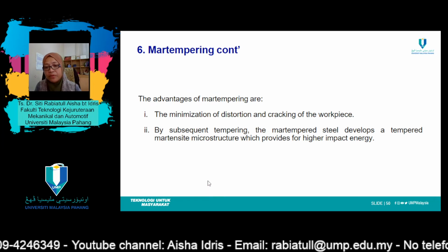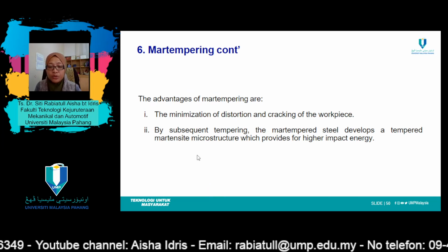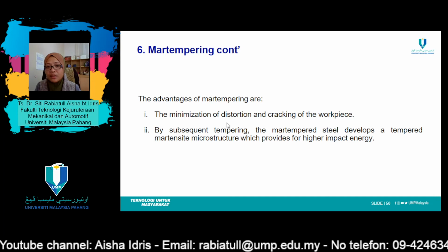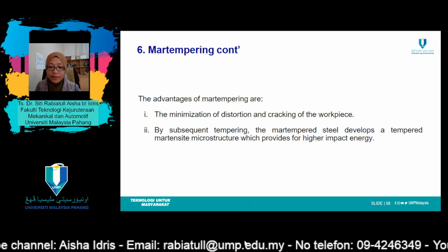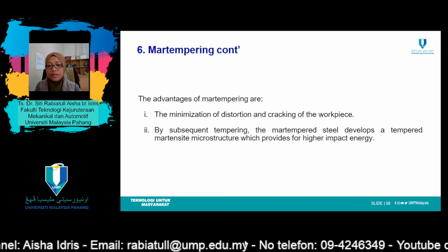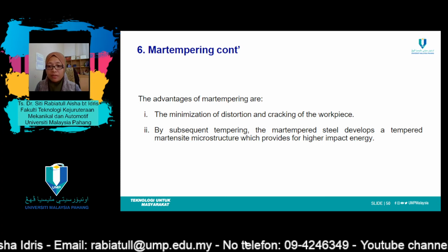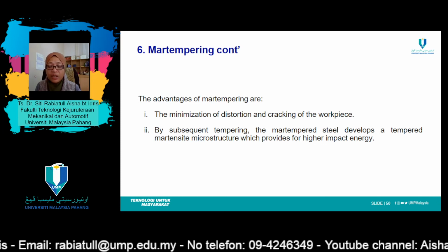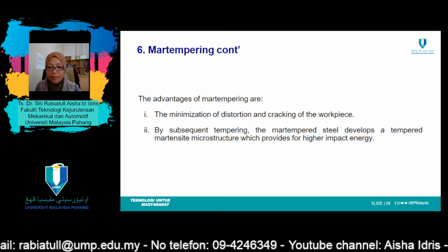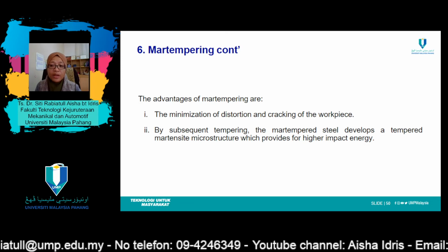The benefits of martempering are to minimize the distortion and cracking of the workpiece. Number 2, by subsequent tempering, the martempered steel develops a tempered martensite microstructure, which provides higher impact energy.